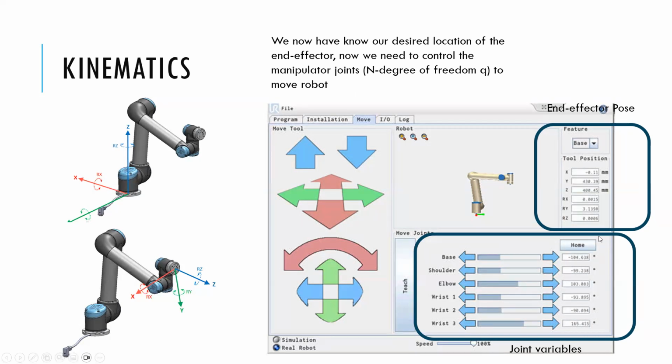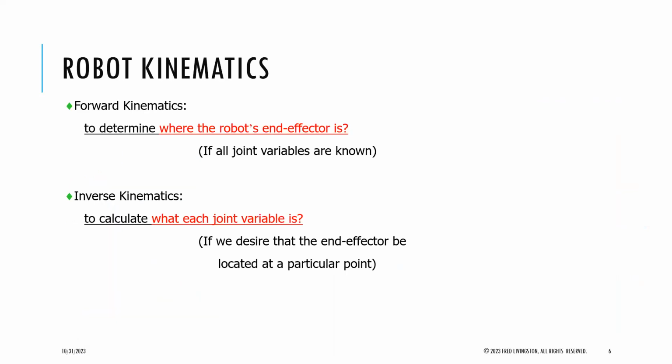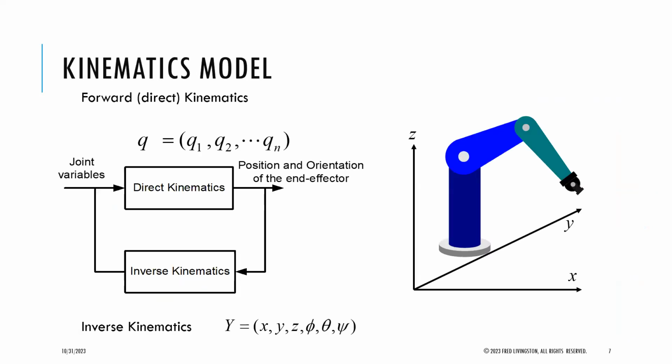And there's a lot of libraries that solve for that already. We showed you how to do that during the chain method, but I'm going to show you some more examples of that today using some other methods. So the forward kinematics is, where is the end effector? How do you determine that given the joints? And then the other direction is the inverse kinematics.